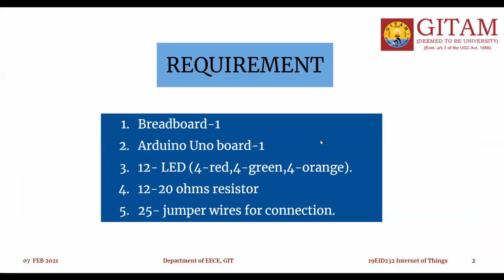We need requirements like one breadboard, one Arduino board, 12 LED lights. There are 4 red LED lights, 4 green LED lights, and 4 orange LED lights, 12 20-ohm resistors and 25 jumper wires for connection.